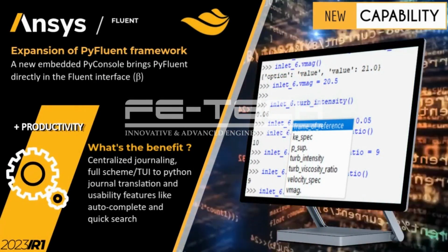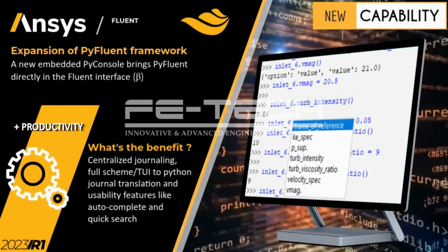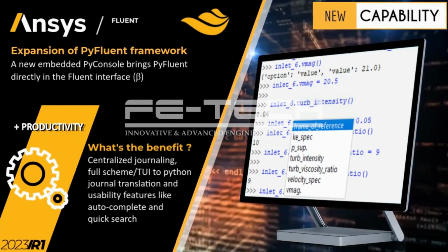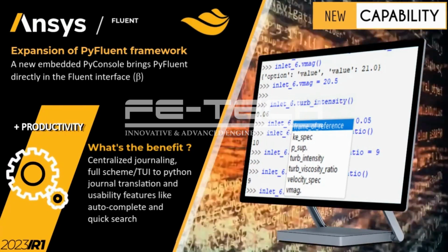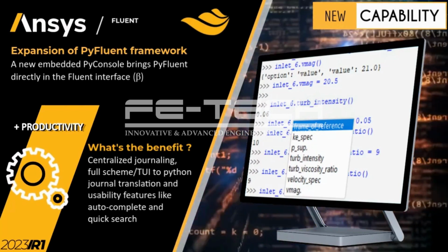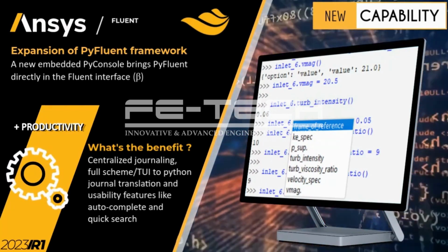A new embedded PyConsole brings PyFluent directly into the Fluent interface, with support for centralized Python journaling, full-scheme TUI to Python journal translation, and usability features like autocomplete and a quick search of Fluent's commands.